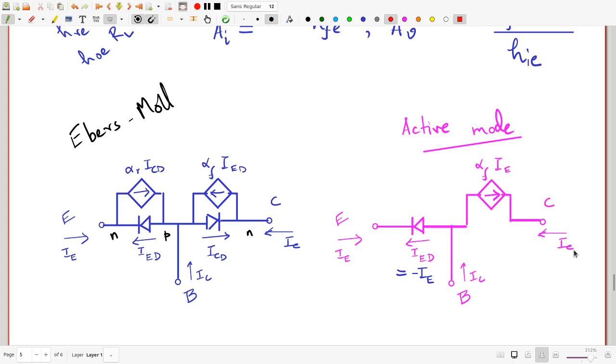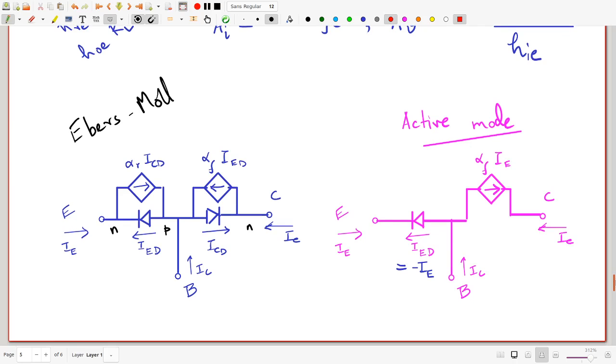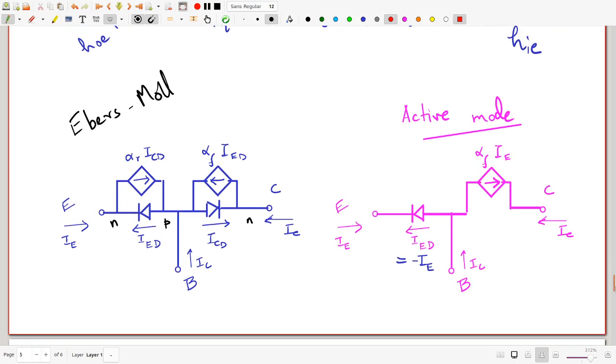We already talked about how to use this in the DC bias calculations, where what we did was essentially replace the diode by the cut-in voltage, which is the voltage drop across a forward bias diode. Now that is for the DC part of the calculation. Now what we want to do is talk about the AC part, or fluctuations. Now the thing is really rather simple.